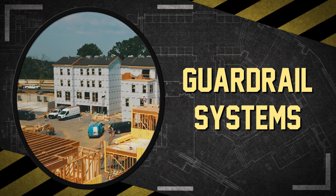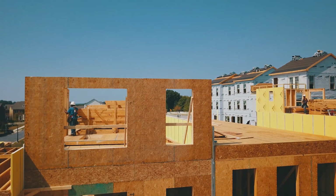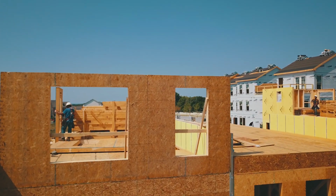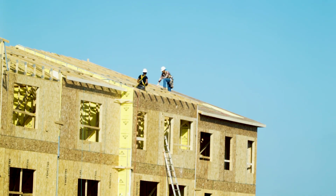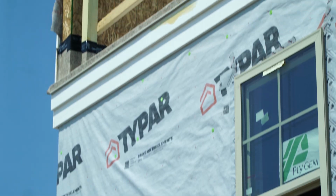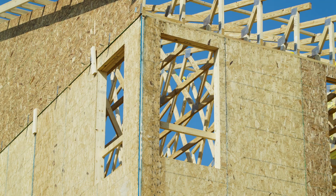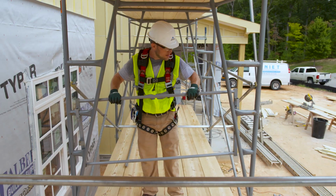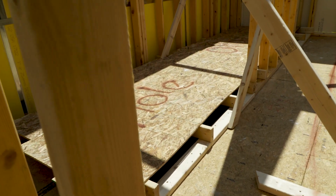Nearly all construction sites have unprotected sides, edges, wall openings, or floor holes at some point, which pose a hazard to the workers moving around the job site. These openings and sides must be protected with guardrails or covers. Guardrails are a fall protection system that is a barrier preventing workers as well as job site visitors from falling off a walkway, landing, or working surface, or through a hole.